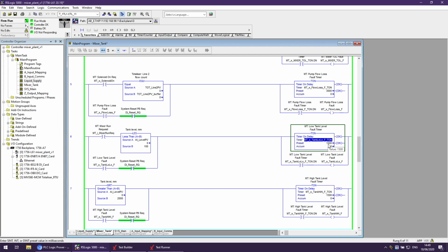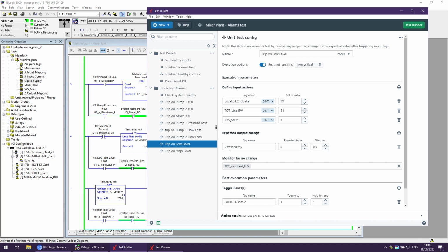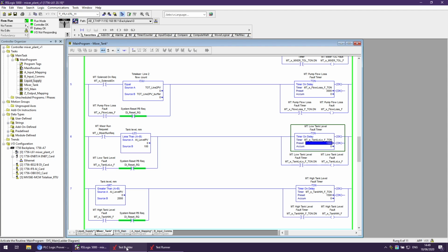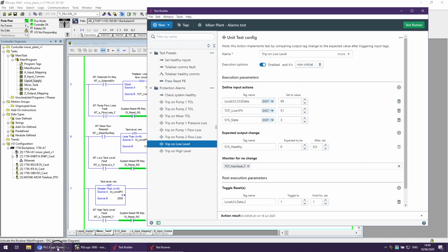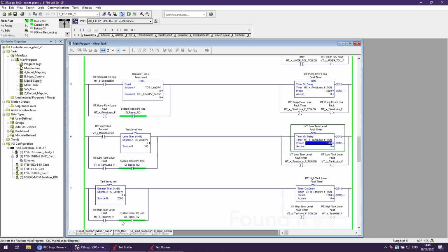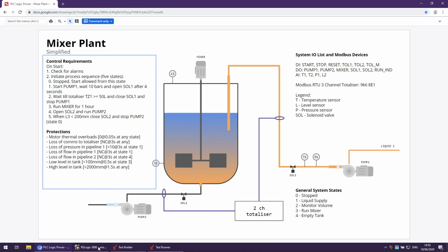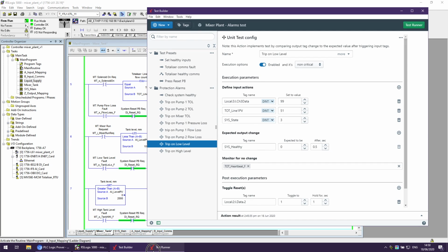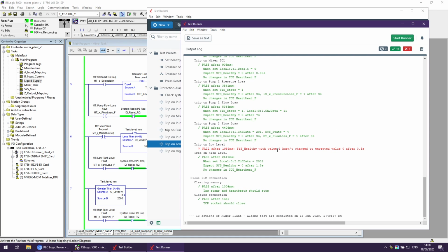And what do we have here? 0.5, so it's 500 milliseconds, and we have 1.5. And let's go back to our functional spec. It says 0.5. So that is a perfect example when we have maybe copy and paste from here or here, the blocks, and we just changing values and forgot to change presets. So in our case, PLC must have half of second as per our functional spec. So let's go back again and try to run this again. And I think that is caused that issue.